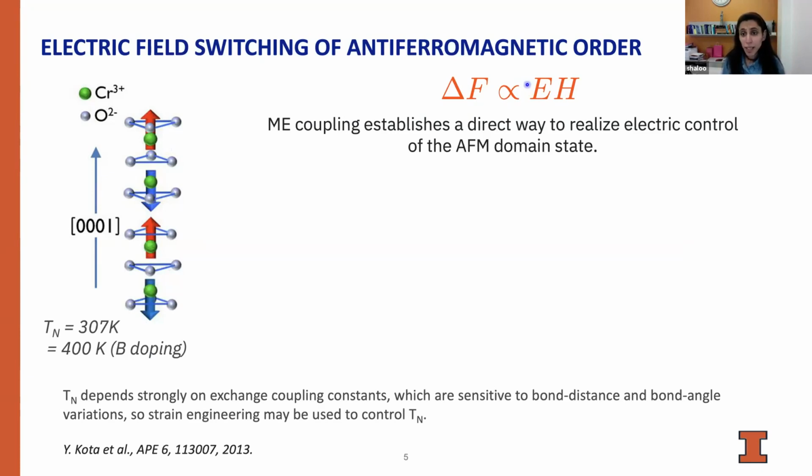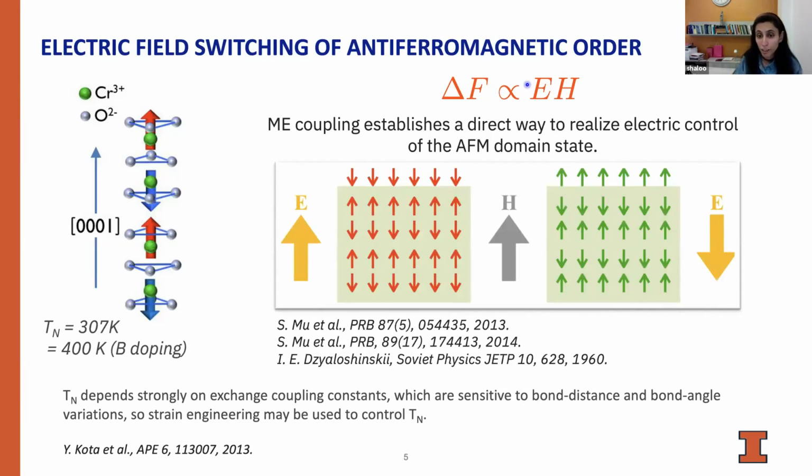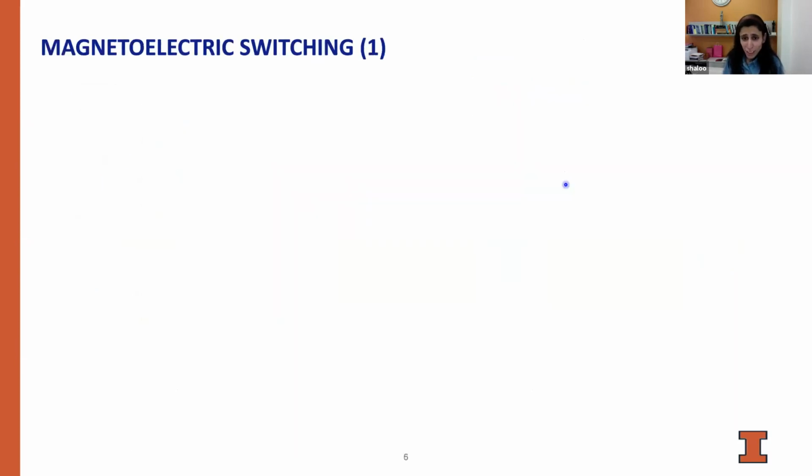But the nice thing about this magnetoelectric effect is that we can directly electrically control the antiferromagnetic domain state, as I'm showing in the figure here. So chromium does contain roughness-insensitive boundary magnetization that is coupled one-to-one with its bulk antiferromagnetic order. And we can then apply a constant value of the magnetic field, a small one, and then we can change the polarity of the electric field and switch the antiferromagnetic order and the boundary magnetization. And this can then be read either using an exchange bias setup or a ferromagnetic free layer setup, and so on. So this is very interesting.